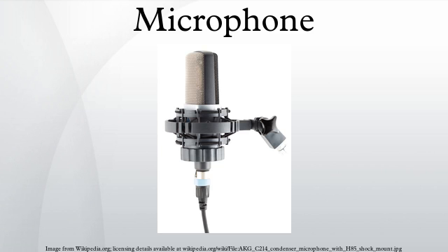Electret condenser microphone. An electret microphone is a type of capacitor microphone invented by Gerhard Sessler and Jim West at Bell Laboratories in 1962. The externally applied charge described above under condenser microphones is replaced by a permanent charge in an electret material. An electret is a ferroelectric material that has been permanently electrically charged or polarized. The name comes from electrostatic and magnet. A static charge is embedded in an electret by alignment of the static charges in the material, much the way a magnet is made by aligning the magnetic domains in a piece of iron.